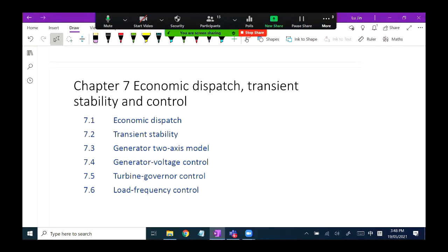The second model for this part has some constraints, the constraint optimization model. In such a case, the power generated by the generators cannot go infinitely big. It will be constrained within a small range. Based on this, how do we determine the optimal value of lambda, the incremental running cost, and calculate the cost value? This is a small extension. If you have such constraints applied to your generators, normally the running cost depends on the generator which is not running at the constraint value. Okay, this is the second model.